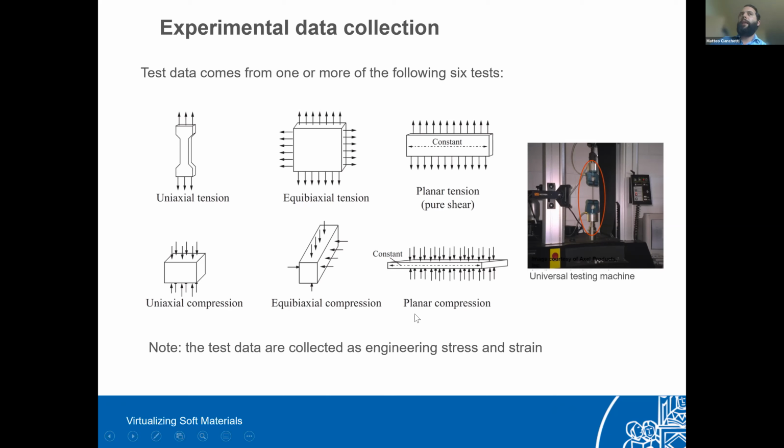Note that for all the models that we saw in the presentation, the data should be collected and expressed as engineering stresses and strains. We saw the difference at the beginning of the presentation.